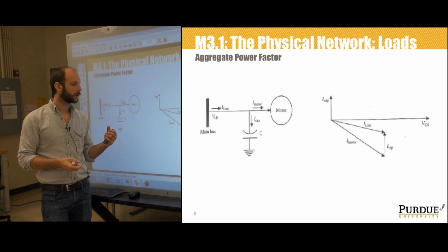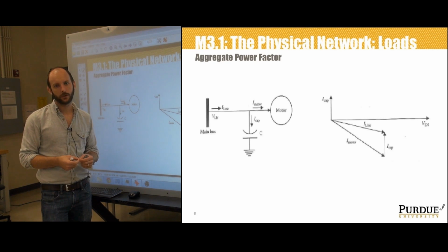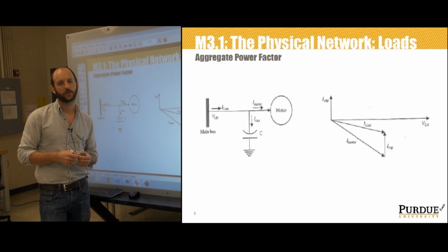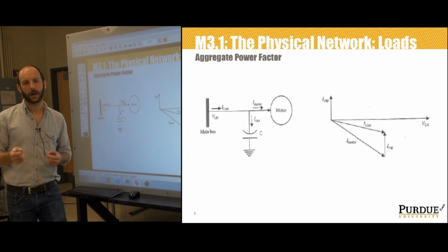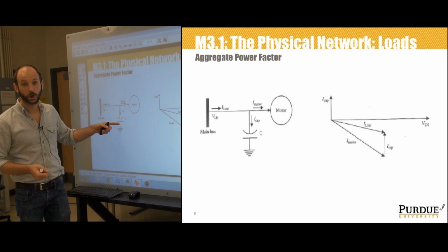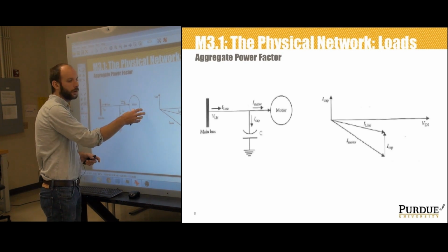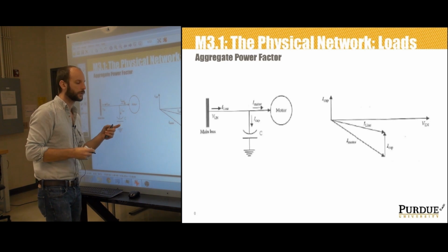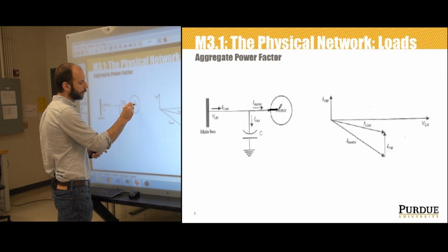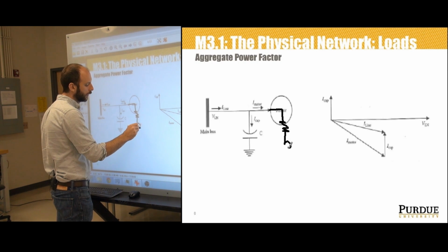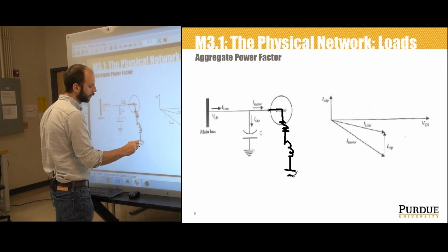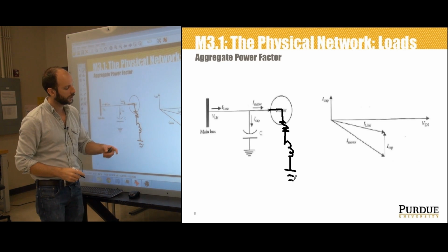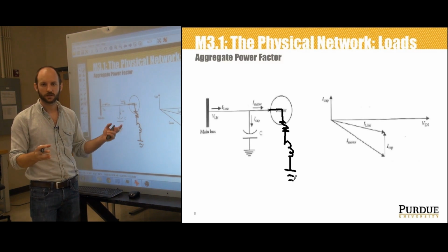Therefore, the power factor in most circuits can be improved by compensating for the extra inductance by connecting a capacitor or bank of capacitors in parallel with the load. We're kind of showing that here. We've got a motor. We haven't looked at the circuit diagrams of motors officially yet, but we've talked about it enough in examples that you know that motor looks like a resistor in series with an inductor, a very simple motor